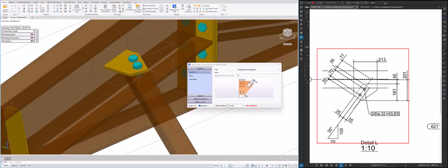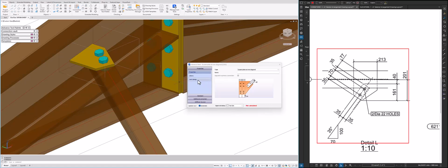So let's start editing. Library and design, we're not worried about that. We go to standard. Our gusset plate, remember, is 8mm thickness. That's good, so we edit there. Then item 2 says distance diagonal 1 to profile. If you check the small image there, it will show you that 2 is the distance from the main member to the edge of the diagonal, or our angle brace.